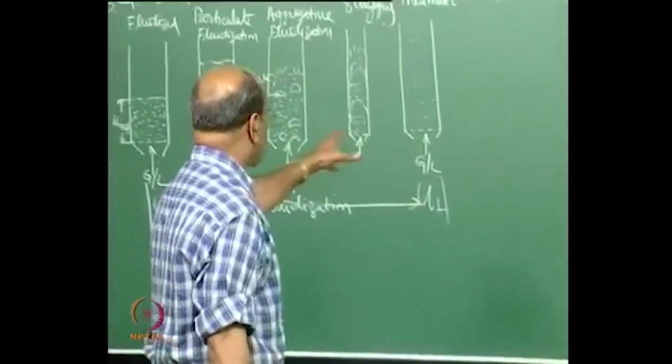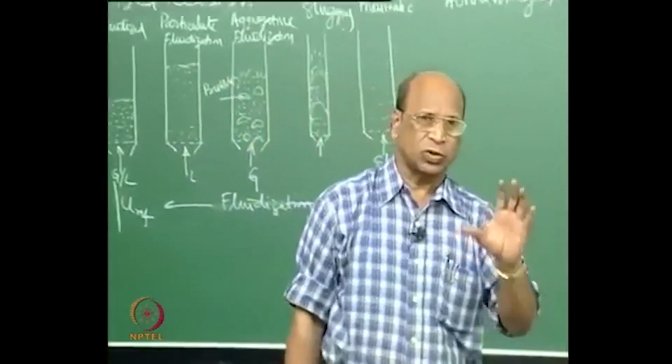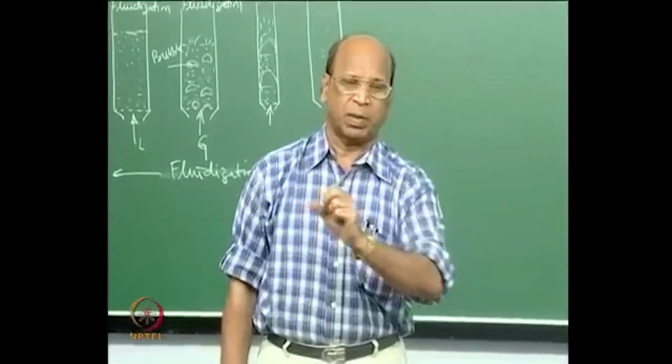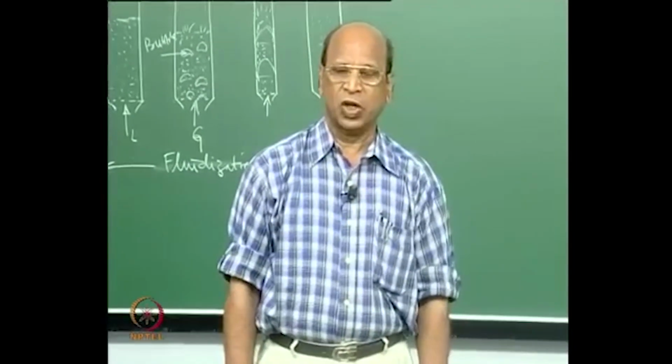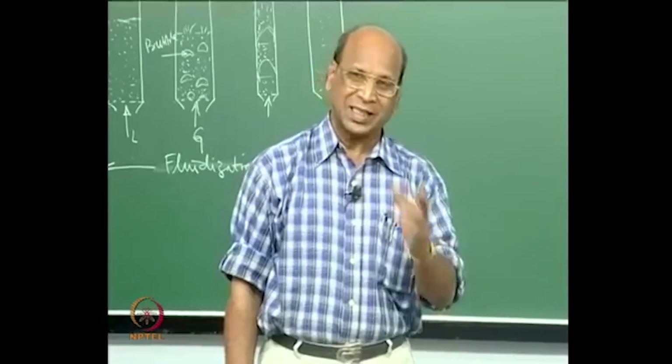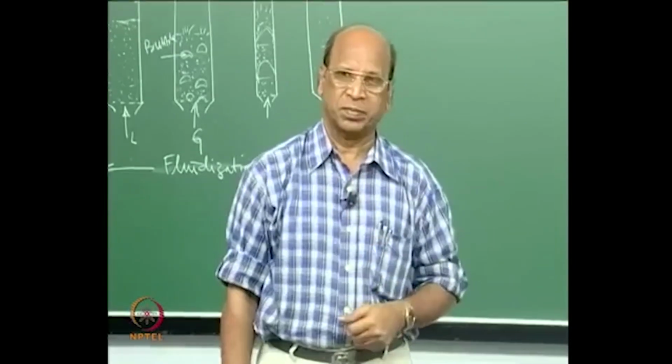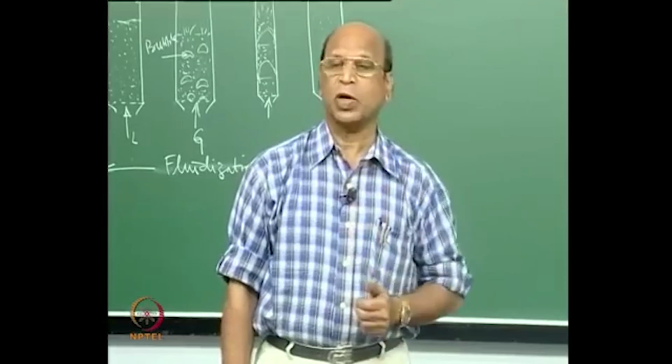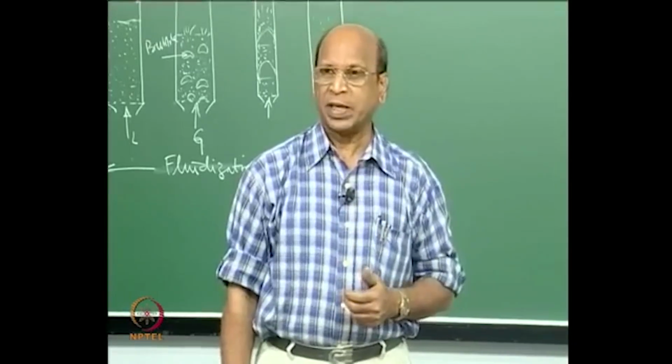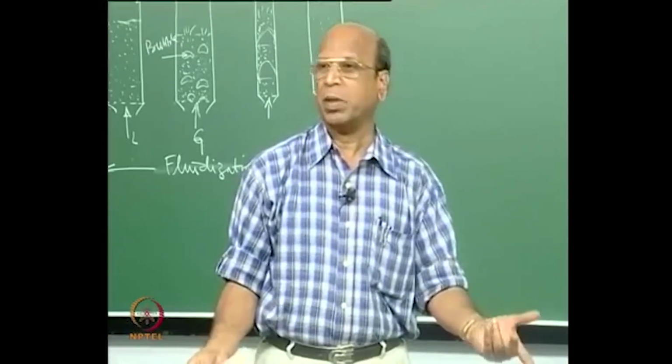Okay, so this fluidized bed, is it equivalent to a CSTR or a plug flow reactor? Solids are in perfect mixing condition. Is it a disadvantage or advantage for reaction? That is one of the disadvantages. Why? Because the concentration gradient is not much.